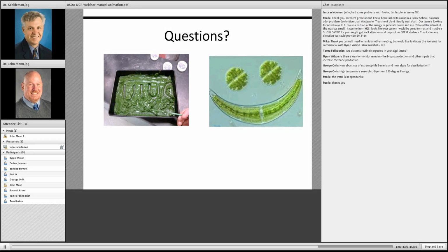We don't try to encourage the diatoms because silica is essentially an ash product, so it moves through your system, and you can still do the hydrothermal liquefaction, but you have a higher amount of ash product because of the skeletons associated with the diatom. So it still works, but it gives you a little bit more of a byproduct to deal with in terms of the ash product that comes off. So my preference is to go for green algae and or for cyanobacteria, but if you get some of the other components, they can be converted into oil.